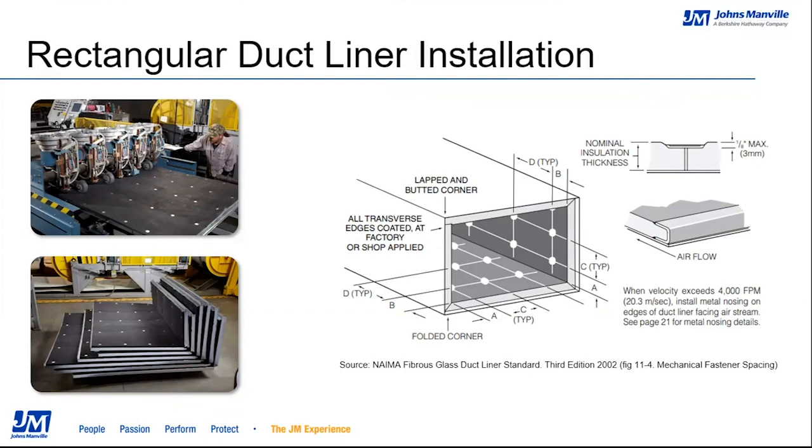What you can see here on the left-hand side, the top picture is a snapshot of after the duct liner has been applied to a sheet metal piece on a coil line. The product has been laid down on a flat piece of sheet metal, glued to the metal, and then those pins are being driven into the product, mechanically holding it down with a weld pin. The bottom section, they'll typically bring that duct a little bit further down that coil line. It'll then go through a brake. That brake will turn it into an L section in this scenario, and two L sections will come together to create your rectangular duct.